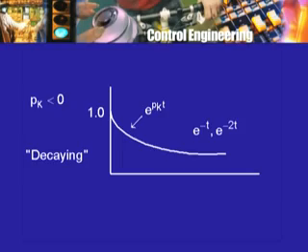And I have told you that after 5 time constants or 10 time constants, maybe 20 time constants if you wish, the function e to the minus 2t is almost 0. It's 10 raised to minus 5 or something of that sort, which can be ignored because all these variables are never known to a precision which is much greater than that anyway. So exponentially decaying is no problem at all. It only says that that part of the response goes to 0. But what we can find out from the root pk is the time constant, that is, the decay takes place with a certain time constant that corresponds to the root pk.